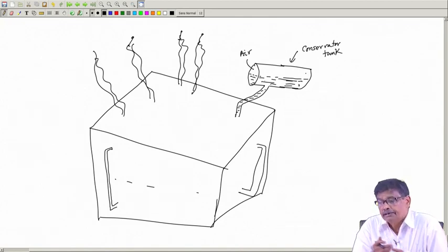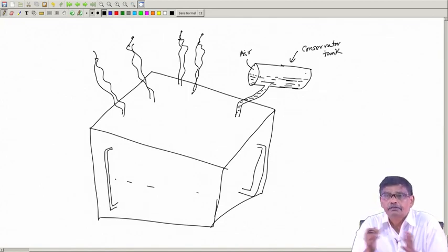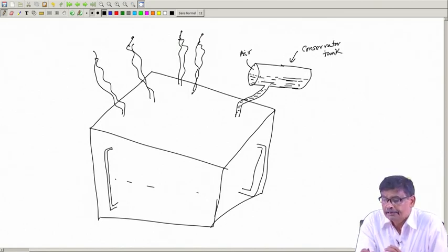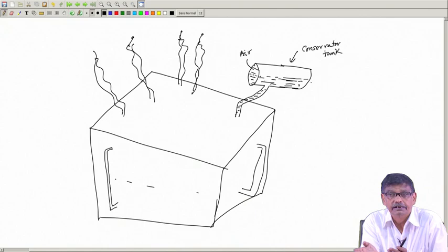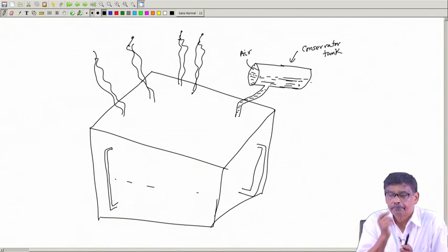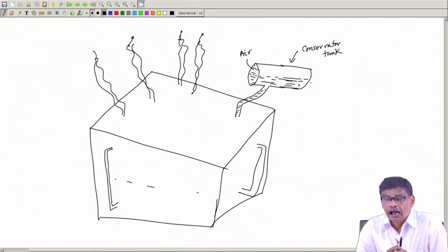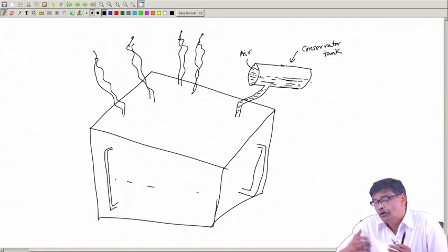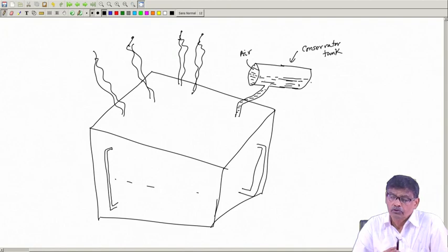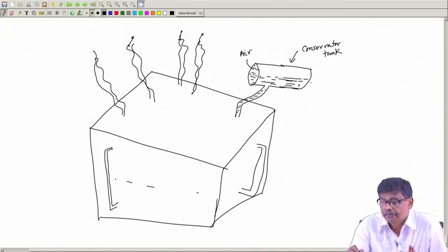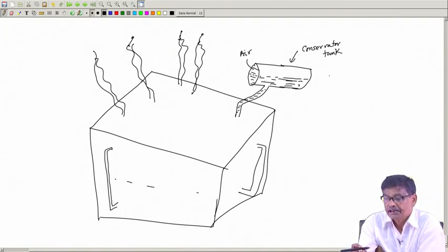If temperature rises, oil is a liquid, it will expand and this level of oil will go up, pushing the air, whatever it was above it, it will be pushed up, is not? And if you go on overloading, level of oil will go up and up. So, there must be some interface with air, it should not be sealed at the top.